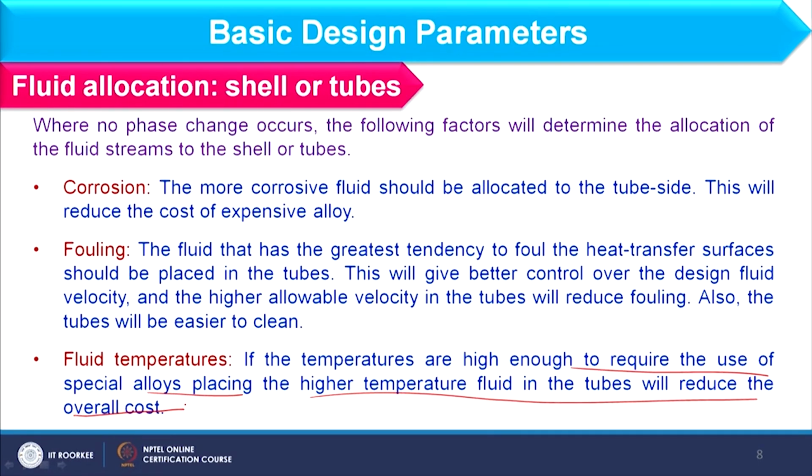The material plays a role by making the tube or shell. Whatever material is involved in the tube or shell directly gives the cost. Material involvement means the thickness of the shell or the thickness of the tube, fine.